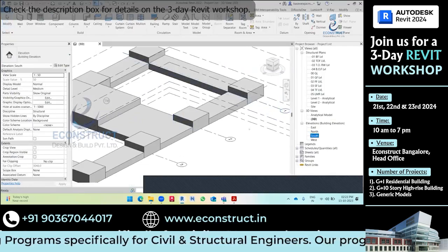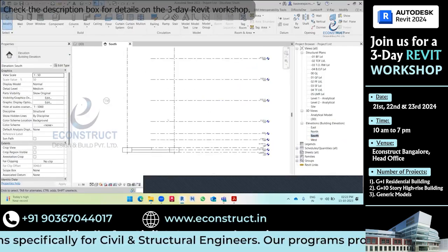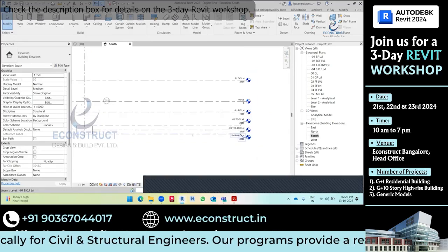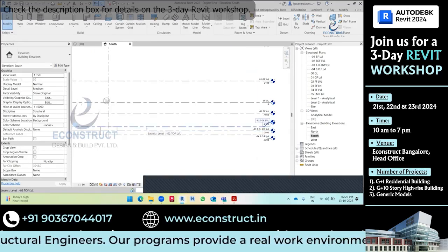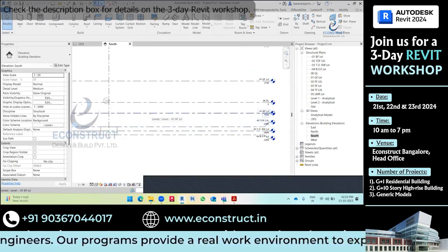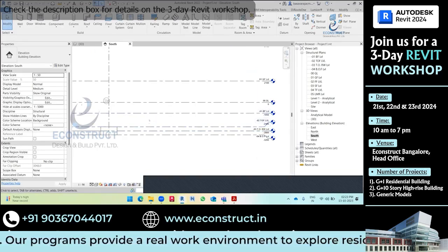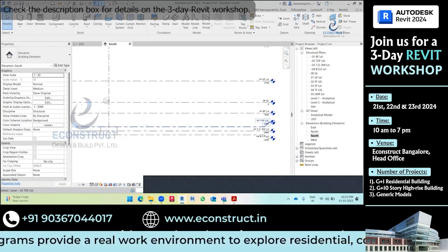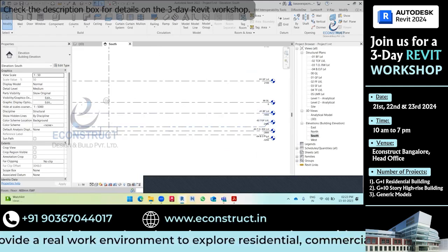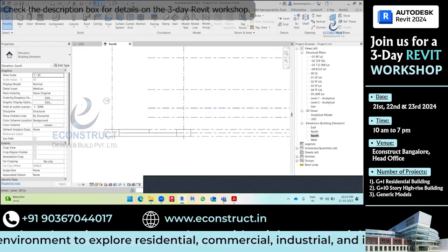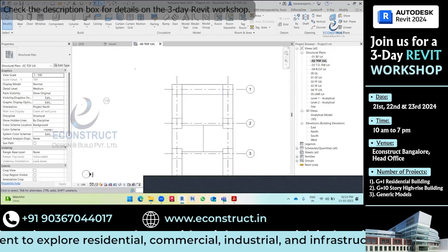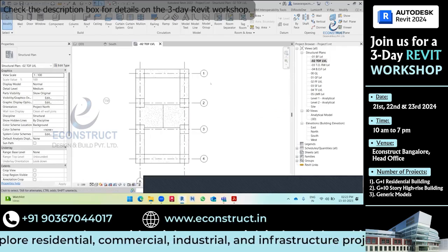I will go to one elevation view. In this elevation view, we need to create the columns from the top of the footing level to the basement floor level. First we will create the columns from the top of the footing level to basement floor level. This we call a neck column. Okay, so I will go to the top of the footing level. We are in the top of the footing level now.